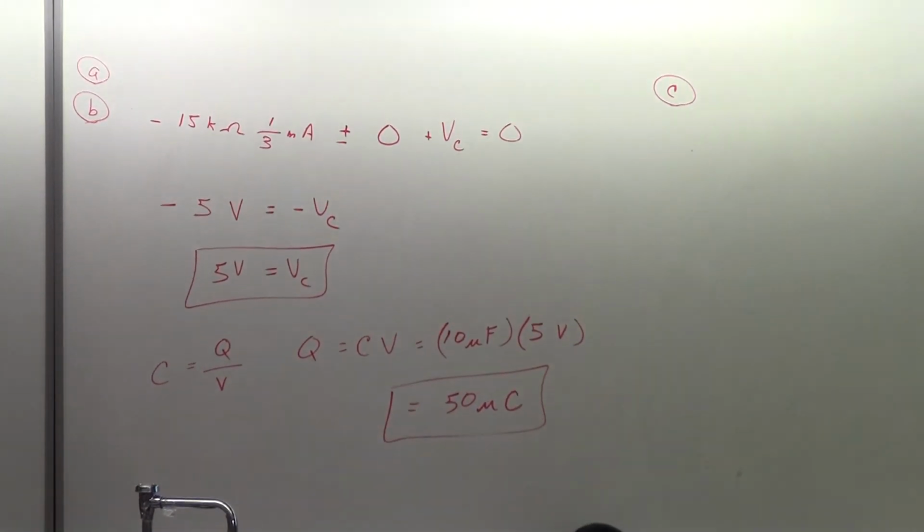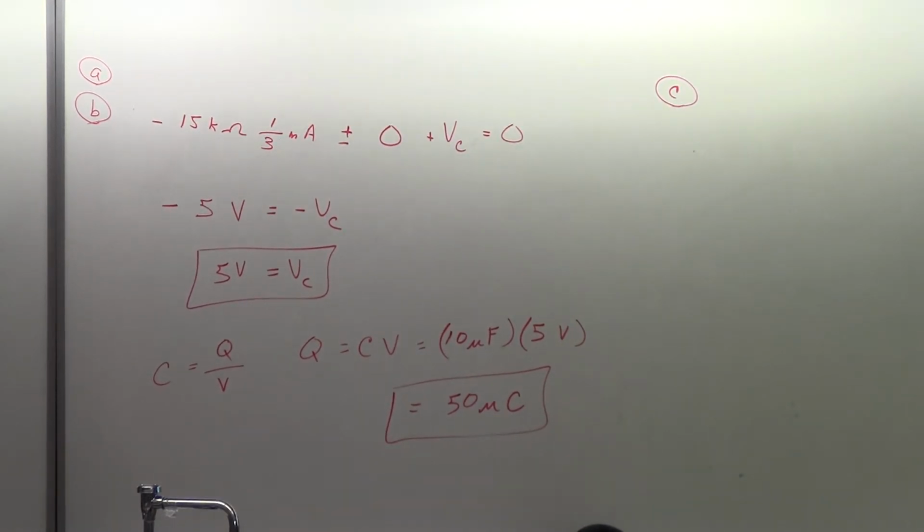And obviously if you know one, you know the other. So the real trick is finding either the voltage or the charge, and that leads you to the other one. And in this case, the real trick was to realize that there'd be no current in that far loop after a long period of time, and then we can get the current in here, and from that we can do this second loop and get it. So again, notice I just used Kirchhoff's loop rule. Do the voltages, whatever math you get, solve the math.